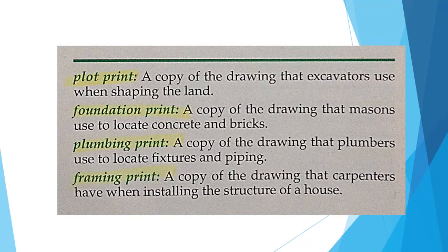At first, this may seem to be a type of print that an electrician would not have to review. After all, water and electricity are supposed to be separated at all times. Actually, it is a good reason to have a plumbing print. It is easier to avoid the plumbing lines and fixtures when you know where they all are to be installed. Another reason to review the plumbing print is to locate electrical devices for items such as hot tubs, water heaters, washing machines, and even yard sprinklers.